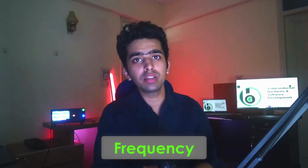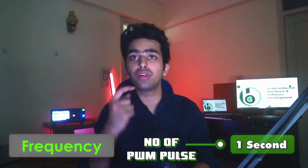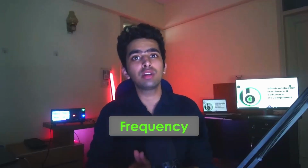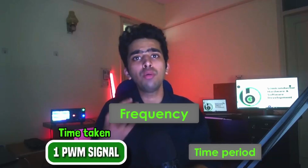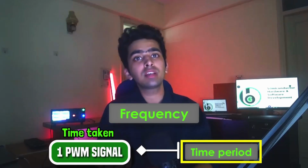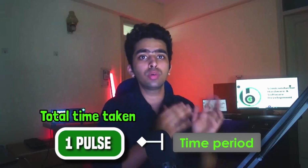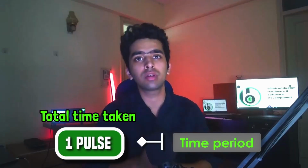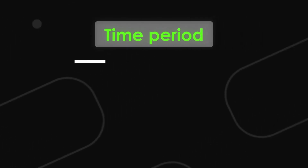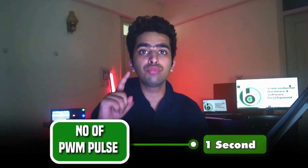The next parameter is the frequency. Frequency is the number of PWM pulses in 1 second. So frequency is calculated by first determining how much time it takes for one PWM signal to complete, and that is basically the time period that we have just analyzed. The time period is the total time taken for one pulse to complete, and then we divide 1 by this time period value so as to get how many pulses would be there in 1 second.